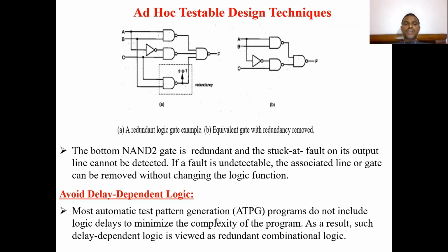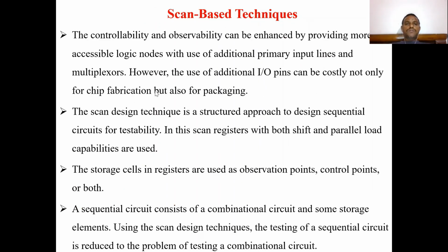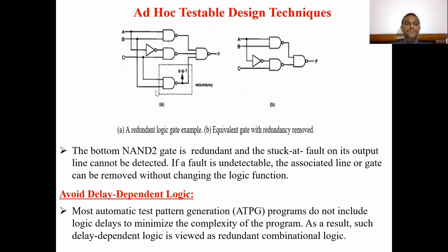Generally these test pattern generators do not include logic delays, to minimize the complexity of the program. As a result, such delay dependent logic is viewed as redundant combinational logic. These are the ad hoc testable design techniques.